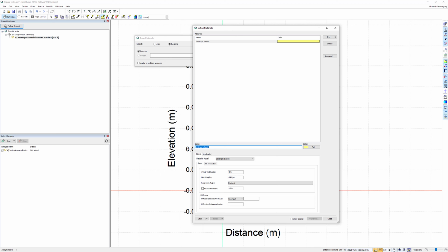It follows then that the material model we choose to simulate consolidation in Sigma W doesn't really matter, so long as we reach the desired stress state, which might be impossible if the sample starts yielding if we were to use an elastoplastic material model. To simplify our lives and speed up calculations, it is best to use an isotropic elastic model for this purpose. All I need to do is fill out the basic model properties. The void ratio I input here is irrelevant, as I will be discarding any deformation that may occur during the stress initialization anyway.